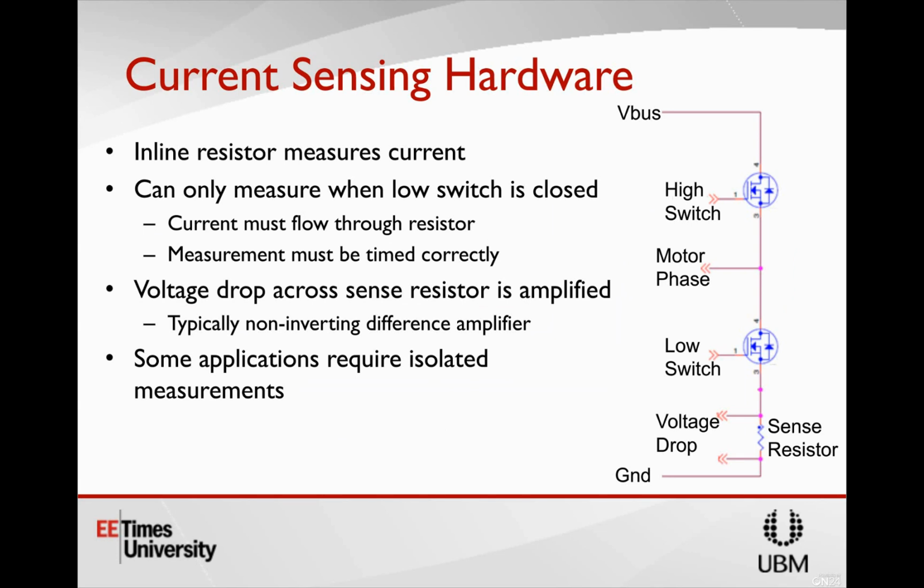But one thing that's important to keep in mind about field-oriented control and being able to sense the phase current is you actually don't need to sense the phase current in all three phases. It isn't required. It will give you the best performance, but it's not required in all applications. And the reason you don't need to do that is because the sum of the three phase currents is 0 based on Kirchhoff's current law. I said that wrong yesterday too.